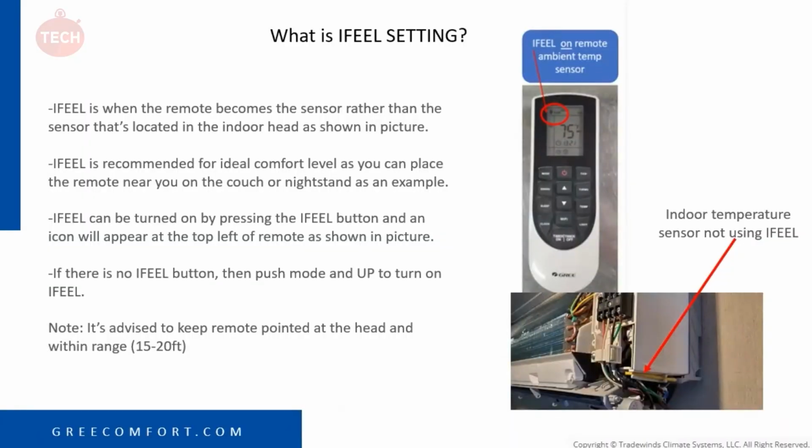What is the I Feel setting? Again, there is an I Feel button on the remote. If there is not an I Feel button, push mode and up together, and that will turn on I Feel. When I Feel is on, a little emoji will pop up there.